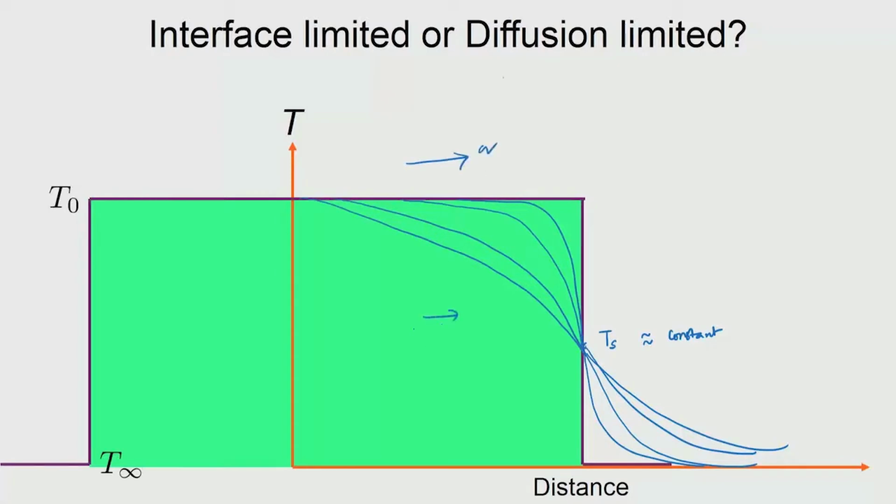So, the heat transfer is now diffusion limited, because as soon as the heat arrives at the interface it is able to go away into the ambient air by the heat transfer coefficient. Here you have Ts minus T infinity. This is readily available. However, the temperature profile inside is not fully evolved, and at the very interior, at the center of the body, you see that the temperature is still T naught, it has not come down at all. So, this is a situation where, for example, you have a non-conducting body like a ceramic, which is exposed to air, and then the temperature is supposed to drop.